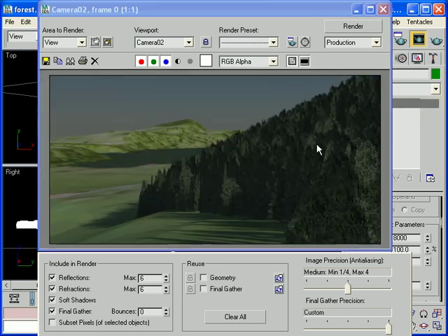And then the end render there. Again, you are going to take a performance hit. On slower machines, it's going to take quite a while. But you have a little different color, different angles, different shadows going on in there. The diffuse bounces I could have set higher, but it would have taken longer to render. Well, that gives you a nice quick forest using a Civil 3D model.